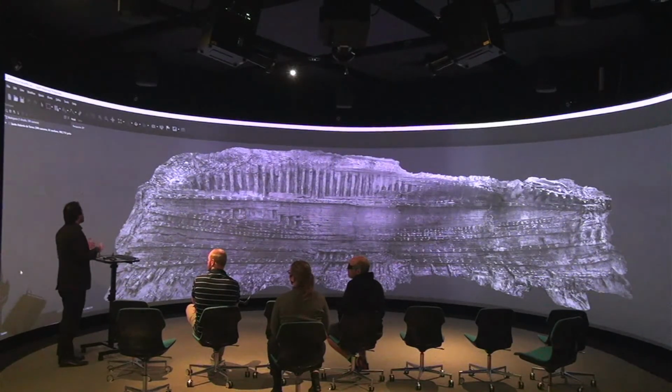You're not aligning and merging them all together at once. You're aligning two chunks together, generating a full 3D model. So chunk 1 and chunk 2 get merged into chunk 3, and then that has to be aligned with all the other chunks, and then everything blows out. So you have to mark versions with a fresh project. And I think this project could have been like 50 gigs for each one of these project files, because there are so many 3D models and so many points that you're duplicating.